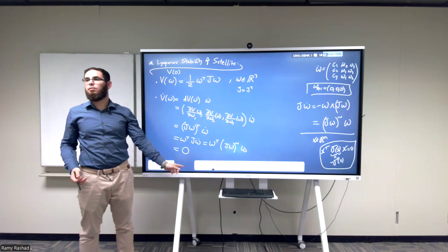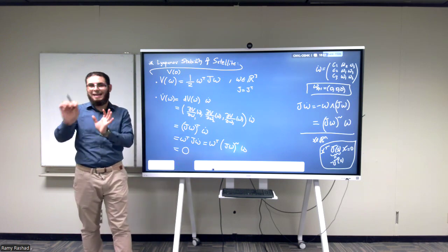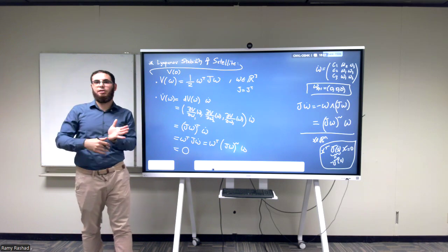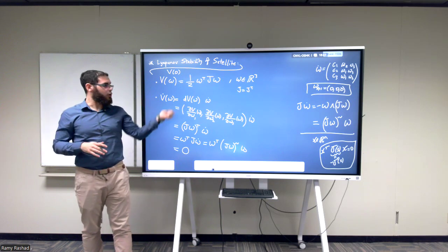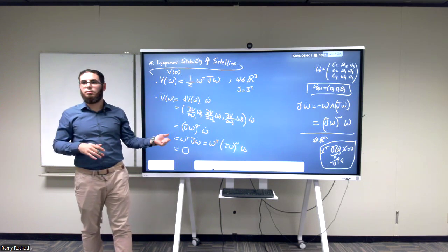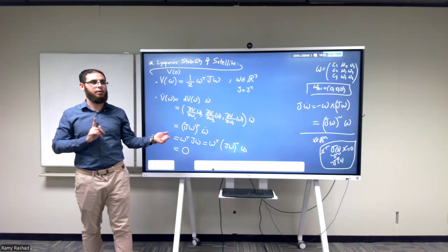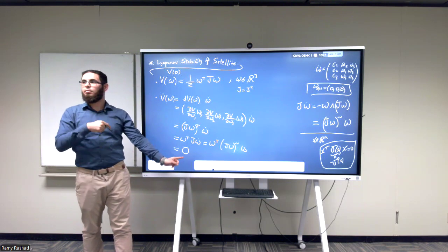What does that mean? It means it's negative semi-definite. It's exactly equal to 0. It's not increasing, and it's not decreasing, which means that it's always stationary. What can you conclude from Lyapunov's theory with this? The origin is only stable, not asymptotically stable. Because if we want this to be asymptotically stable, this should have been decreasing.